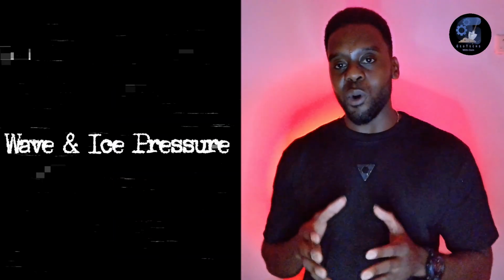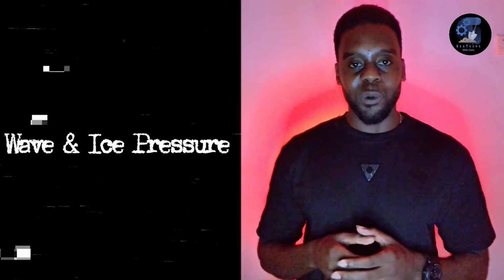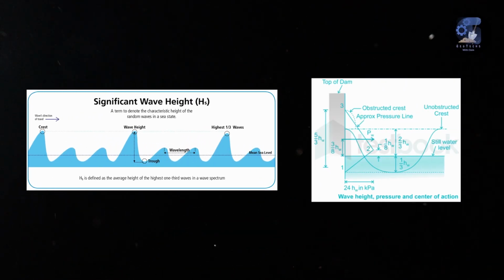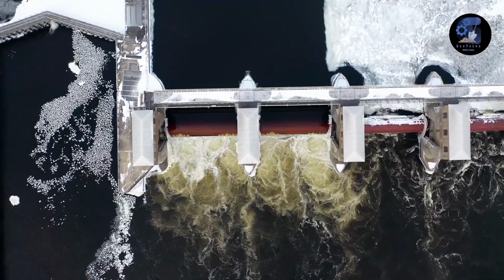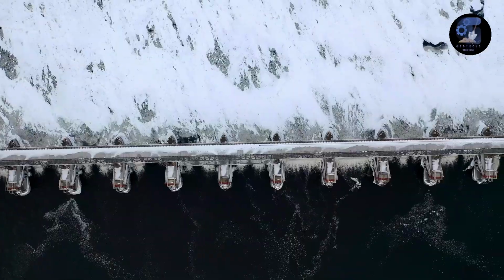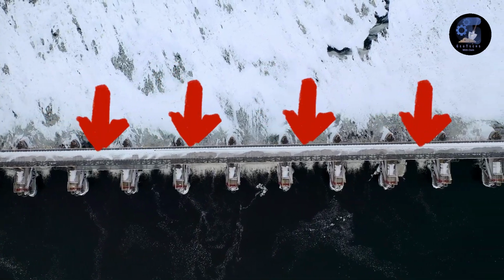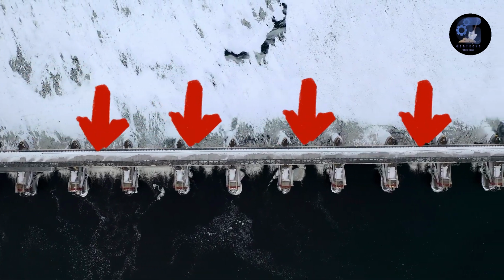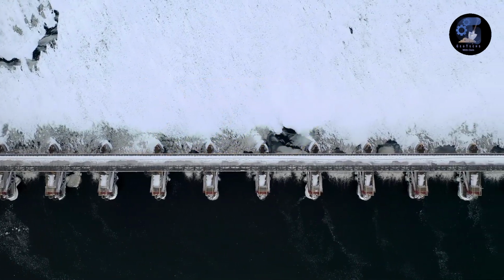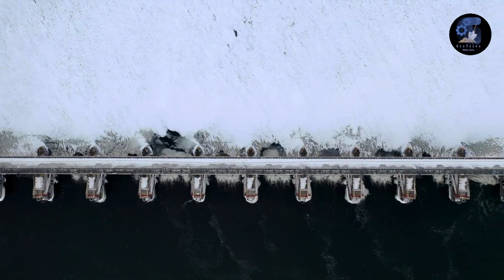Waves generated on the surface of the reservoir by blowing winds cause a horizontal pressure towards the upstream side of the dam. This pressure is heavily dependent on the height of the wave. In cold climate regions, water on the surface of the reservoir freezes and expands. The dam face then has to resist the force exerted by this expanding ice. This force acts linearly along the length of the dam and at the reservoir level.